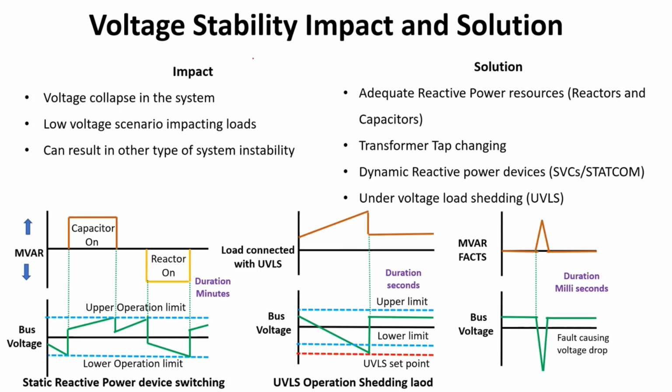The speed governor is there, which will be taking care of all these things. If you go to hydro, you will find a high frequency trip setting, right? And if you go to thermal, you will see that there is a low frequency trip setting on the turbine governor side. You have to maintain that speed control, because otherwise the eccentricity will be lost and too much vibration will be observed. So this kind of control for safety of the equipment is there.